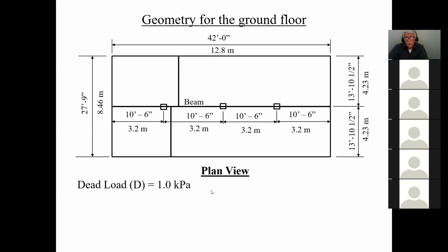I can add it here, assume something. In other words, I can assume, for example, a 5-ply 2x12, which would be the widest, biggest one I would have. How much would that weigh per meter, and then just add it to my WD of my beam, you understand?